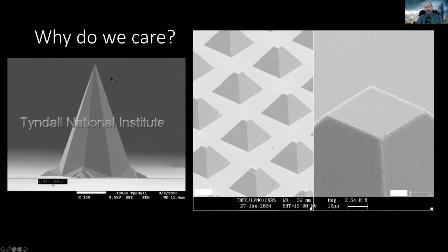So if you make 10,000, 100,000 of these needles in a couple square centimeters or so, you can make a patch. You coat the needles with whatever drug that you want to administer subdermally, and you put the patch on, and it only goes in so far, which you define as an engineer on how you etch these things, you know, how big it is.